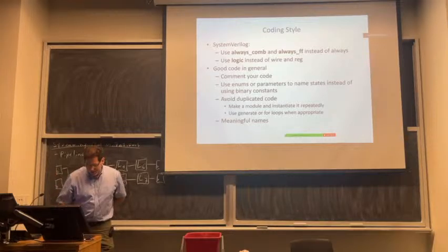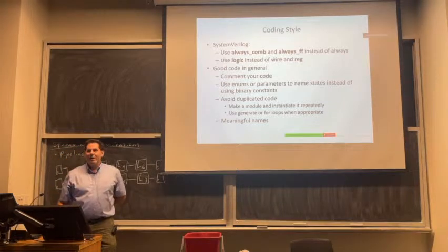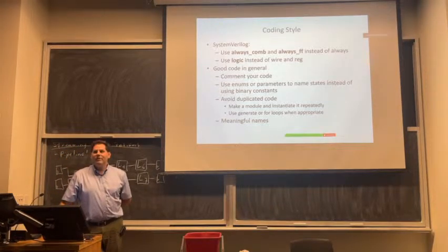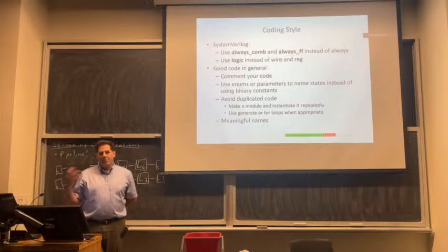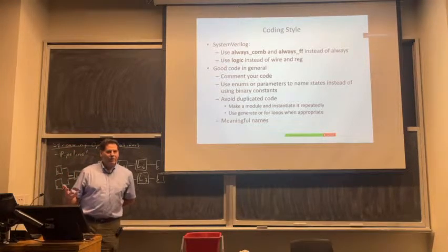The other thing, okay, how many people in Verilog have been confused by what the heck is a wire and what is a reg? And why do they have both these things? I was confused by it. I thought it was bizarre. To think of why it's like that, you actually have to think about how a simulator works. It's not really a design concept. It's pieces of the original simulation design goals of Verilog showing through in the code you actually write. So it's not really desirable.